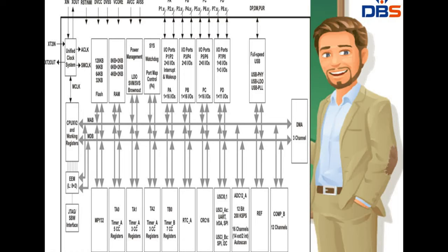It is going to detect that, and the brownout reset circuit resets the device by triggering the POR, power on reset signal, so that the power is applied or removed. Suppose the power is applied, it will get reset. If the power is removed, we are going to check again. We have to start from the basics.